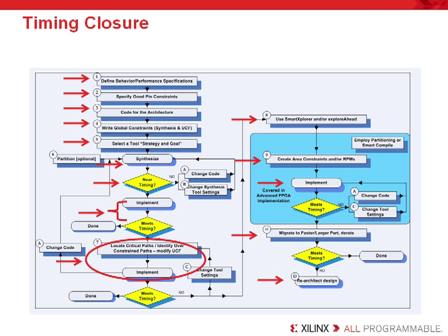Now, next, if that still does not help to meet your timing, then users can consider making area constraints with the PlanAhead software. PlanAhead makes it easy to evaluate the placement of your logic and find a better place and route solution. We'll talk a little bit about that later on. After that, another implementation can be completed, and if you still have not met your timing, then you can try running the tools differently in whatever manner you choose. But now we're starting to get desperate.